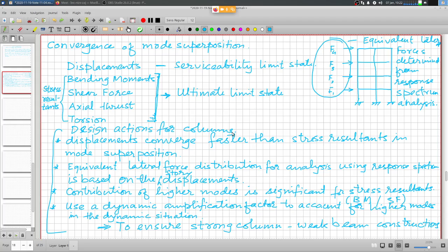If the column carries net tension, then obviously it is acting as a vertical beam, and we can afford plastic deformation with sufficient curvature ductility that may be achievable, and the detailing is also like a beam in vertical orientation.